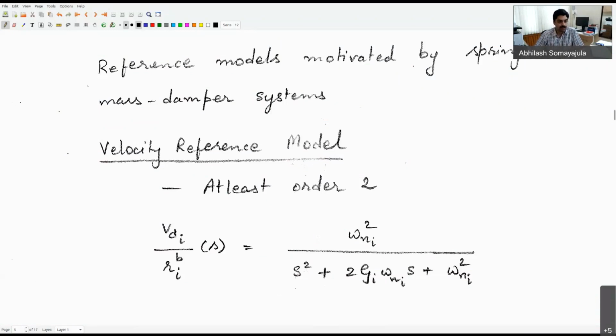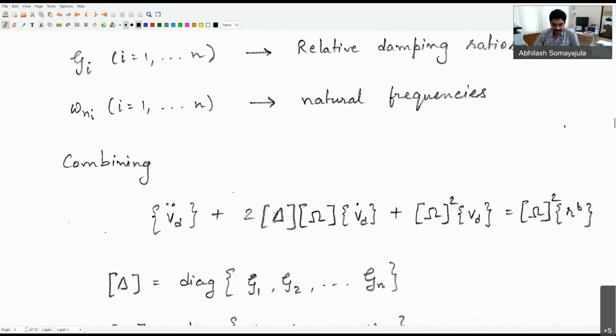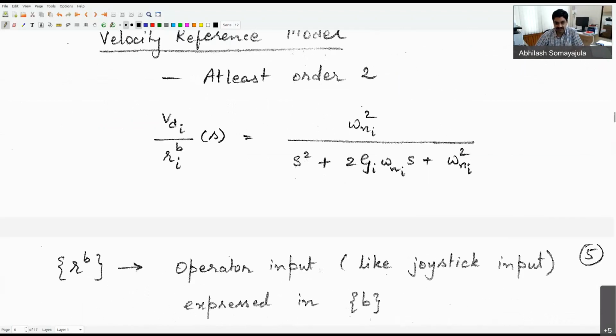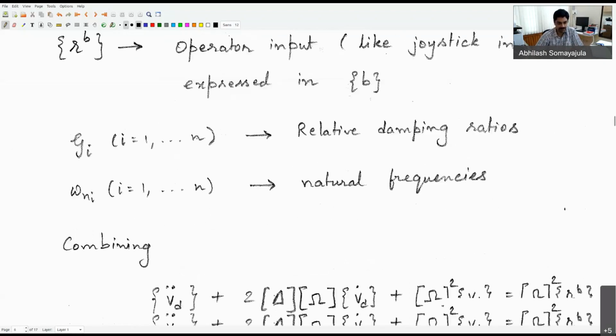Okay. All right, at least the idea here is that it's a second order system, and we talked about this idea yesterday that we can control the damping ratio and the natural frequency of the system in order to tune the shape of the filter, how it should be and what characteristics it should have. We want to tune that as a control designer as to what should be the so-called feasible trajectories which should come as an output.